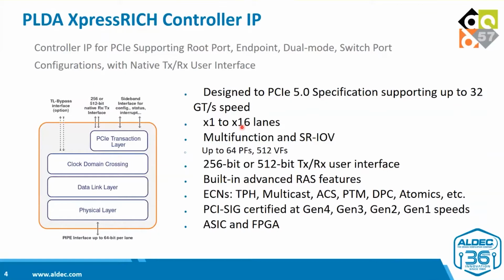It is multifunction and SR-IOV capable, up to 64 PFs and 512 VFs, and VFs can be dynamically allocated to each PF. It also has a built-in RAS feature for reliability, availability, and serviceability. This module adds more rigor to in-depth failure analysis by injecting errors on both the TX and RX paths to check your application as well as the DUT behavior.